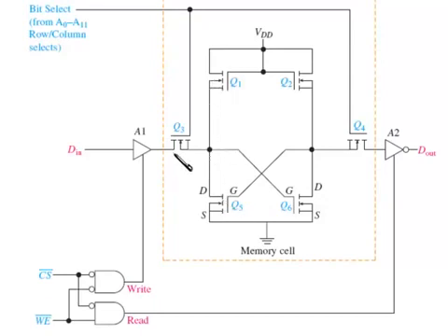And remember, this is a 1 here. This 1 is going to turn this on. VDD will be felt down on this transistor, and so when you remove the data from the input by releasing the chip select or releasing the WE, this becomes an open, but we still have this bias current keeping this transistor on, which produces a 0, which turns this one off. So this cross connection here maintains that 1 in the memory cell by keeping Q6 turned on.